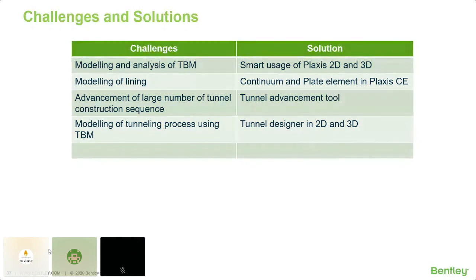But in a newer version of PLAXIS, you can also get the structural forces in the continuum or volume element by using the center line approach. So depending on your expertise and the computational time or computational resources you have, you can choose either a continuum or a plate element.